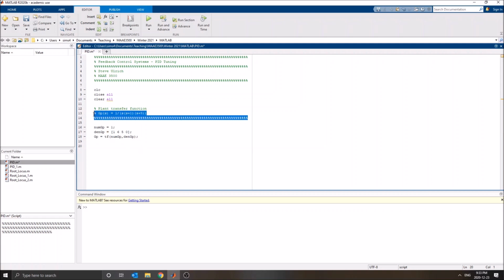Okay. And now that we've defined this transfer function, let's go and verify that the value we found for the critical gain and the critical period match what we see in simulations. Okay, because the work was done analytically on the whiteboard. But just as a sanity check, let's confirm that those two values for the critical gain and the critical period are indeed the right ones. I want to say verify previously determined values of critical gain and critical period.